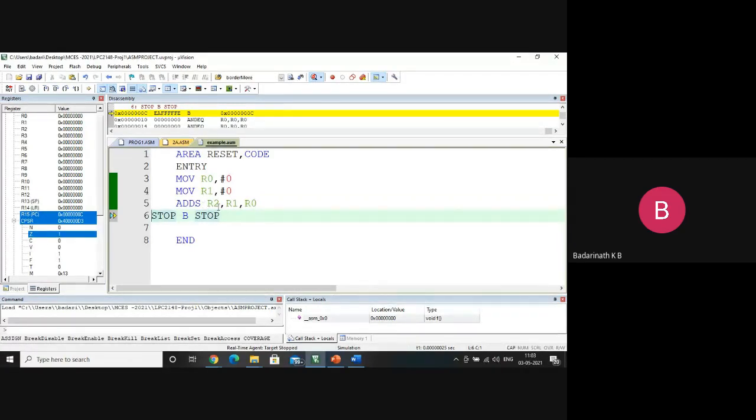Because the answer is produced by this instruction, that is a previous instruction. These flags always talk about the answer of the previous instruction. For example, you have not executed this instruction, which is a previous instruction, add. So these flags always correspond to the latest instruction you executed. The moment you execute the next instruction, the flag reflects the answer of that instruction. So it always talks about the result of the previous instruction. Now, since the answer is 0, 0 is set there.